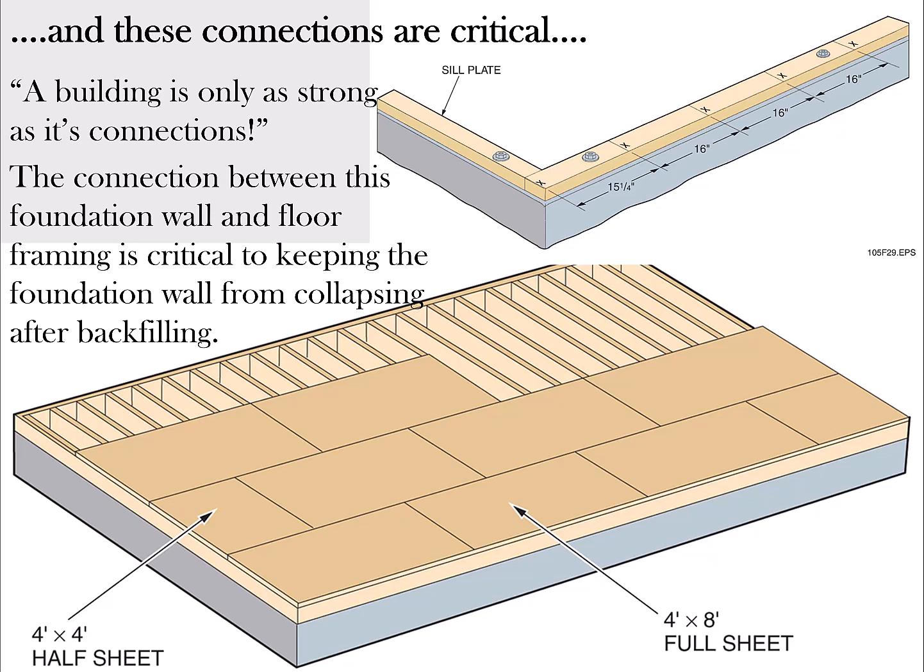Once you've got the frame that you see here, then plywood sheathing helps continue to make it a diaphragm. But that whole wall system has to be connected, typically with metal plates, Simpson Strong-Tie plates, from that wood sill up to the trimmer joists that you see going around the outside here. And then the plywood, where you shift the seams so they're not all in the same place, with a proper nailing pattern. Typically they're glued and nailed, or most often nowadays glued and screwed down, so that they're really rigid and won't squeak over time.